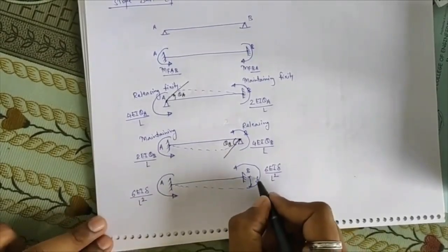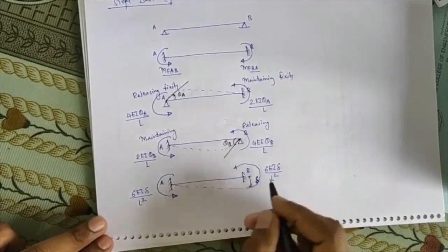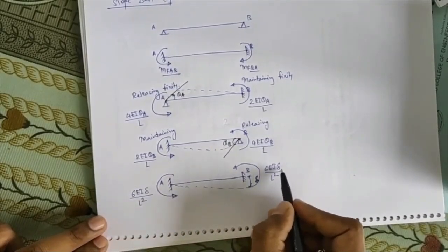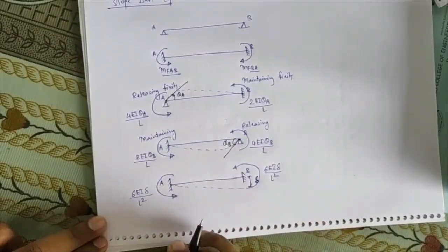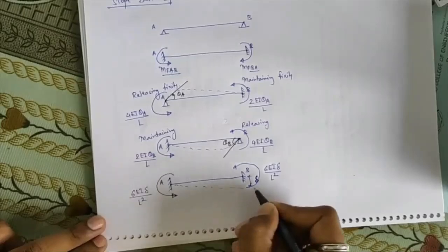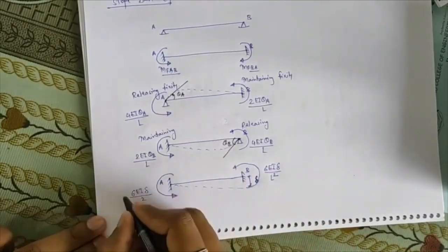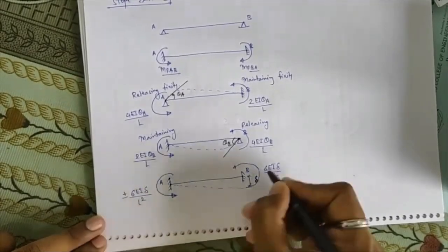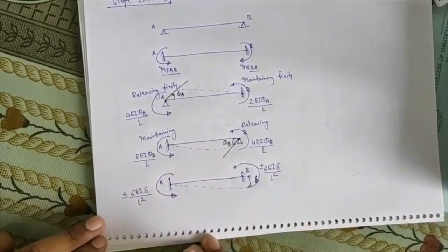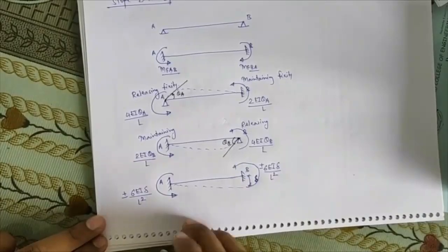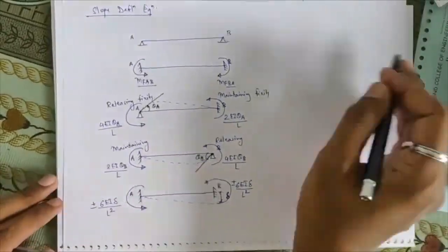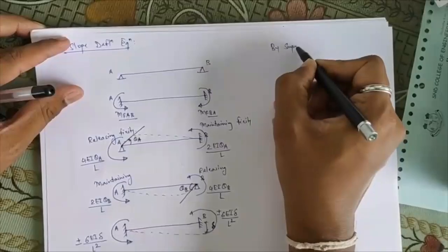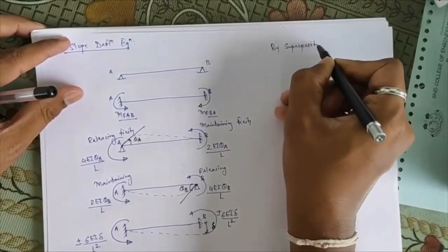The thing is, this displacement amount at both joints, that is at A and joint B, I am considering the same. So I am not writing here delta A or delta B, I am just simply noting it as delta, and depending on the direction of its acting, we need to give its sign. Okay, so either this will be plus or this will be minus. So I am writing plus or minus over here. Okay, now using the method of superposition, by superposition theorem we can say,